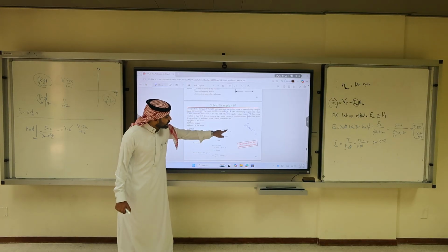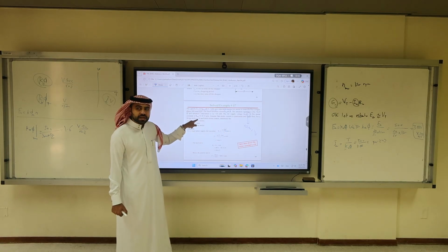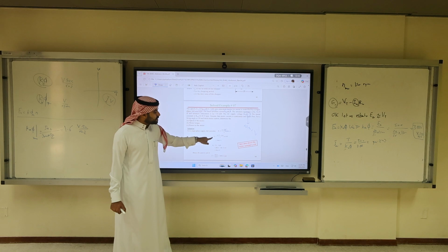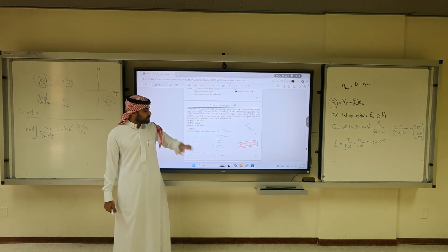So you plug VP here in the equation: 2 square root of 2 over pi times VP times cosine alpha. What is alpha? 30 degrees. So VT is 206. So now we're sending an average value of 206 volts DC.